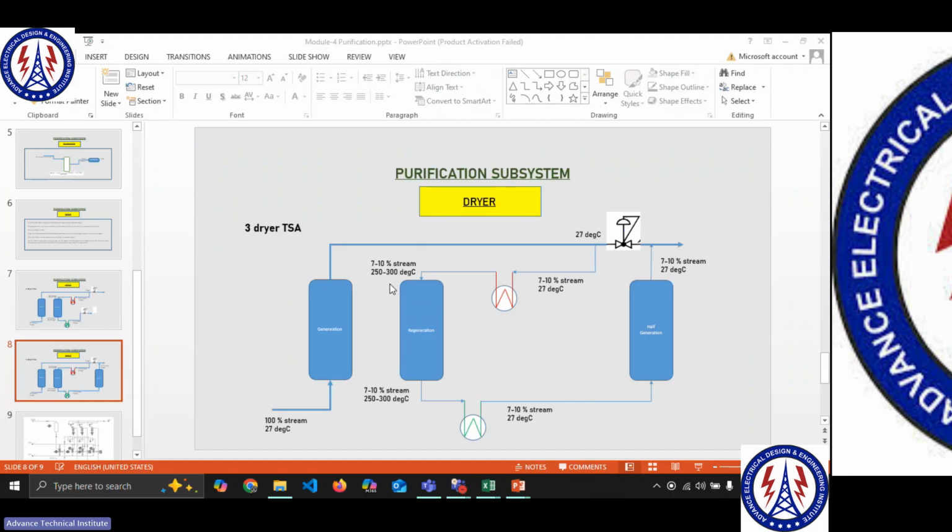Why do you need that temperature? Because if you need to regenerate a desiccant, you need that temperature. See, silica, you can heat up and make it leave moisture. It will go from pink to black to blue again if you heat it. Same thing we have. It is kind of like silica, but a different material, which is better suited for the purpose. Again, fundamentals remain the same. If you heat it up, it will leave out moisture.